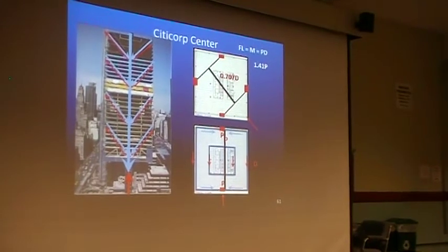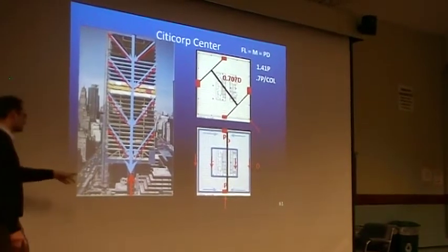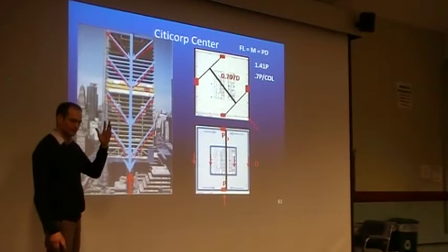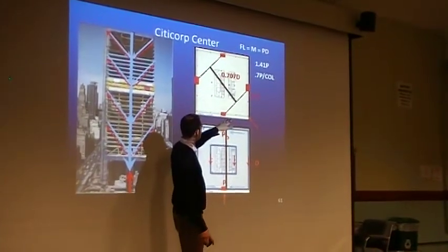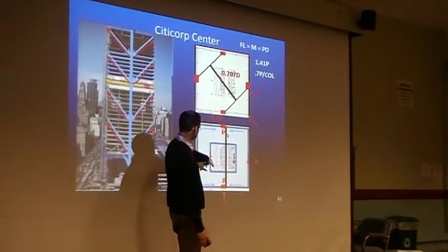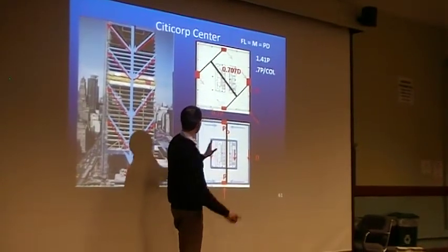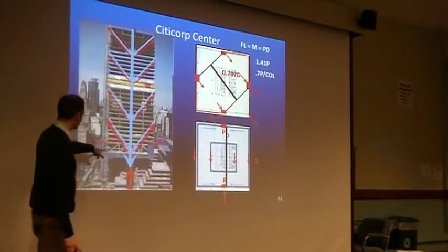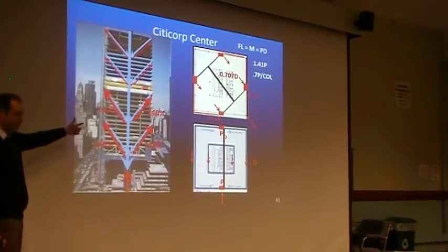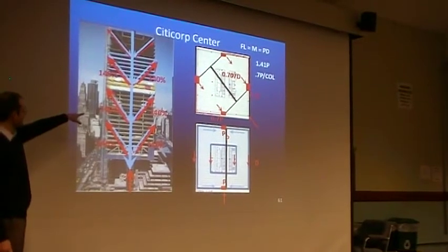So now I've got 40% more tension load than I originally had to worry about. Yeah, it's getting shared per two columns, but now these shear forces, which I've been kind of ignoring up to this point, they whip around the building in kind of a weird way. At the end of the story, all my wind forces, crap, the student's right. I'm about 40% off on all my wind forces.